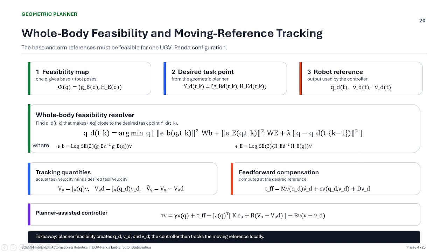So how can we get these desired poses along a smooth trajectory? One of the ideas is to optimize over the pose error for the arm and the base, and minimize it between each two time steps.